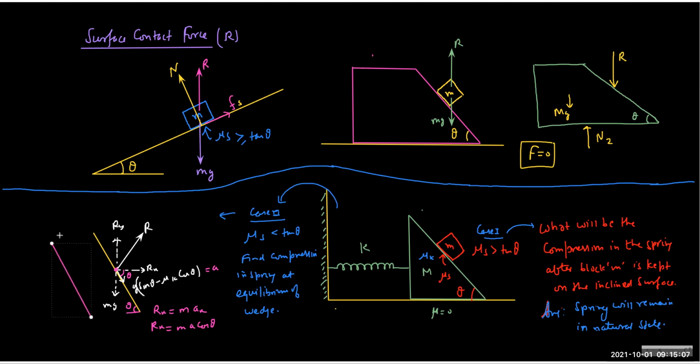if you come back to the wedge part, now this is the biggest realization. Why the concept of R is important. If you solve by the very conventional method, it becomes too lengthy to proceed. Now I know that the Rx is acting on the wedge like this, and that needs to be balanced by the spring force. That's the only thing we need. So the spring force is kx, and now we know that k into x equals m into a into cos theta.